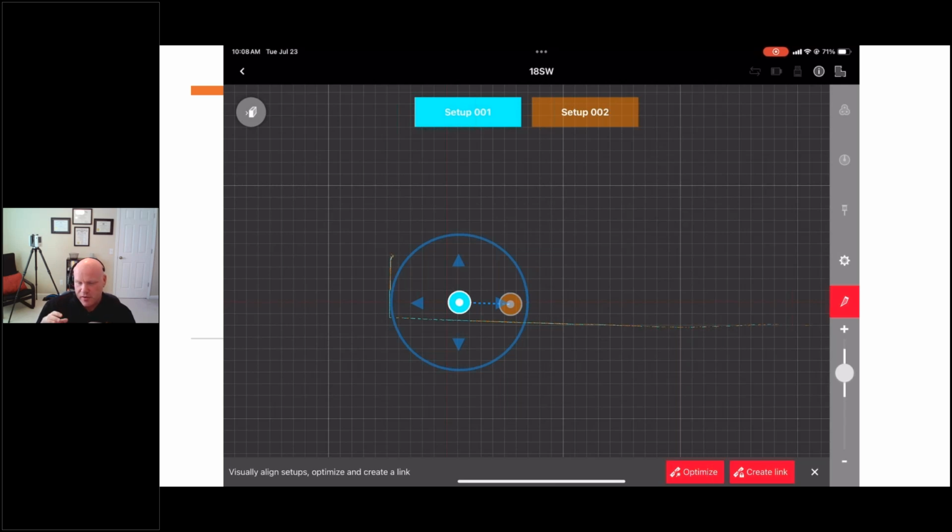But if you're running survey equipment with survey control, I recommend actually leaving high tilt accuracy off, because your tilt accuracy is going to be derived by your total station, or if your site's large enough, by your GNSS.